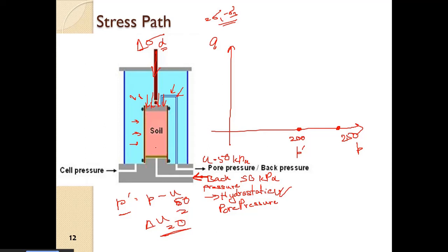So suppose it is 50 now, and we apply shear. Suppose sigma D is equal to 10 kPa, as we have discussed earlier. The pore water pressure develops to 52 or 53 kPa. That 3 kPa pore water pressure, which develops suddenly in an infinitesimal amount of time, will dissipate and drop down to 50. So basically we will consider that excess pore water pressure generation will be zero. Alright, so there is drainage and therefore there will be no excess pore water pressure generation.